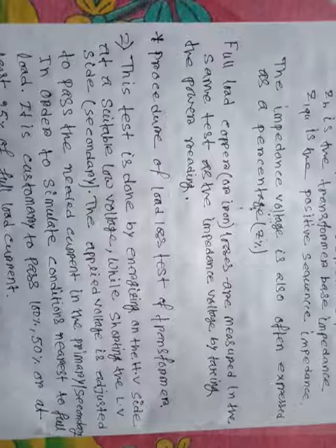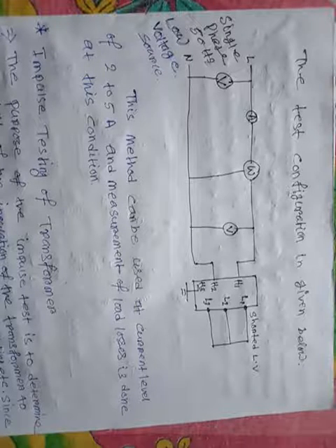One is the load test, another is the no-load test. Load test means the primary side of the transformer is energized and the secondary side is shorted. Secondary side shorted means the load is connected, and in the open-circuit test the secondary side will be open. The test configuration is given below.